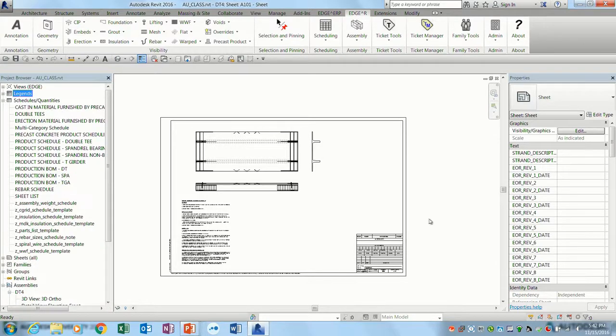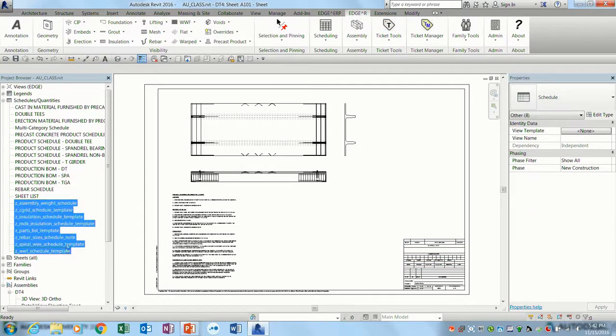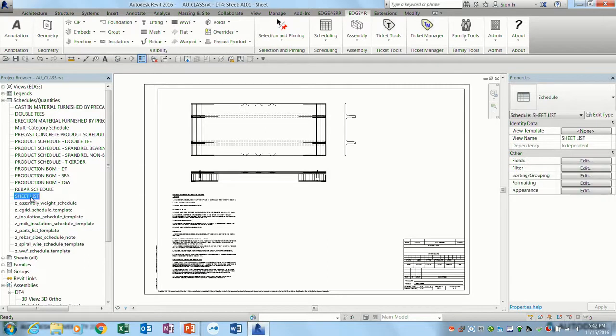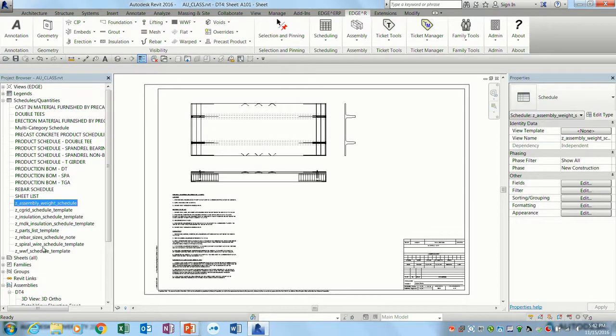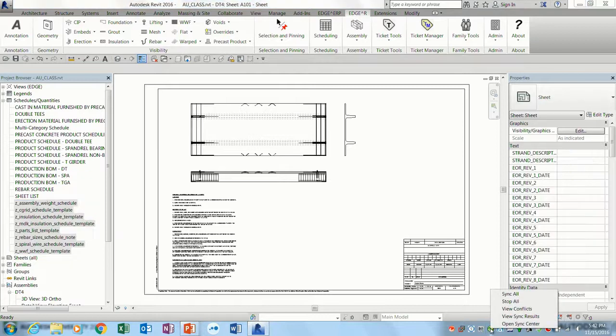He's going to add a note, created the templates, applied the view templates already. One thing that we then did, this problem of the schedules. The problem with this schedule thing is that all the adjusting of the widths of the columns and adding fields and calculated fields and adjusting the formatting, we thought that was a colossal pain in the butt. However, there's no way currently to create a templating thing for that schedule view, to have it automatically placed in the way that we want it.